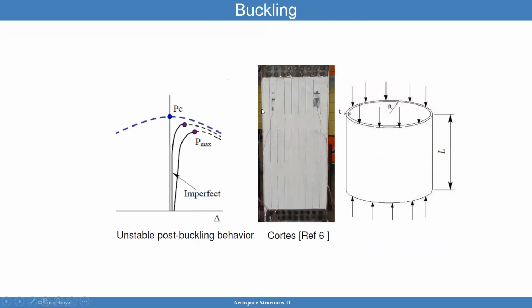It also depends on the imperfection of that plate. The more imperfect it is, the lower the buckling capability you have, because you started with something curved that's going to continue to grow in curvature. A cylinder is similar. A cylinder is going to have a significant amount of buckling reduction with more imperfections included in it. So that's an important consideration that I would like you to consider at this moment in time.